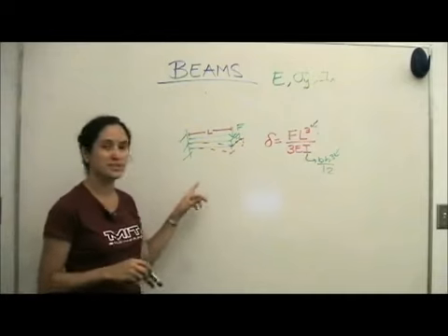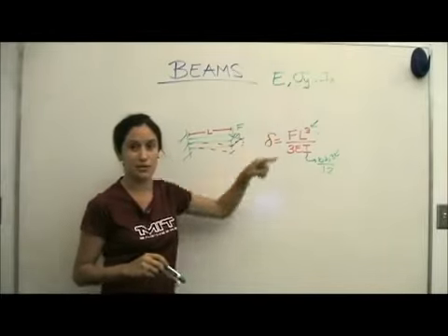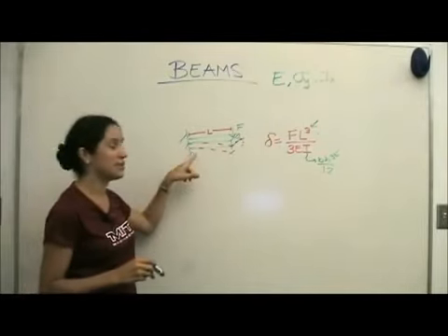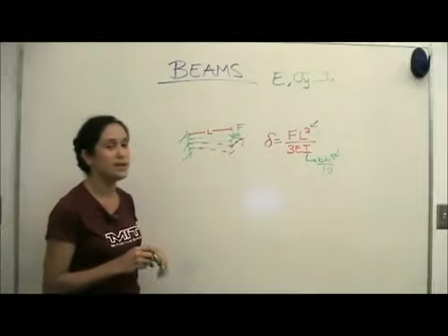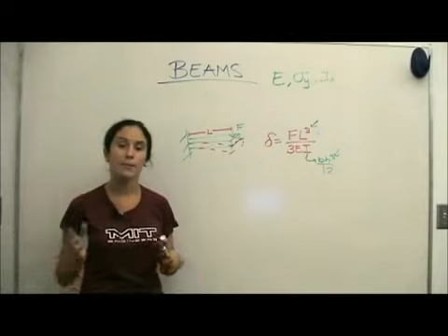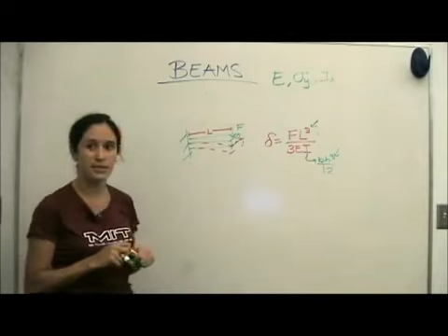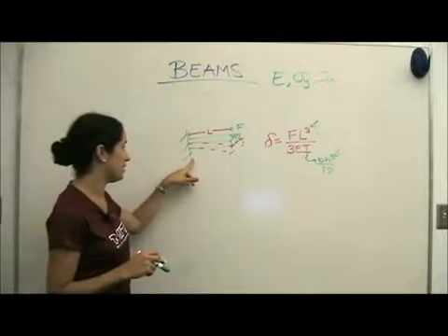The other thing that we're concerned about when we're designing our beam is to ensure that we're not exceeding the yield stress of the beam. So we need to calculate what is the stress on the beam under this load. In reality, both the weight of the beam and the load are putting a stress on the beam. But for now, let's focus on just the external load. To calculate the stress on the beam, we need to understand the bending moment on the beam.